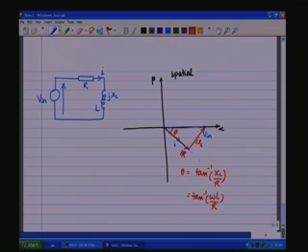Here also you see that the voltage across R, V R, and the voltage across L, V L, vectorially add up to equal V in, such that the voltage across the loop is 0. Kirchhoff's voltage law is valid, and thereby upholding the principle of energy conservation.